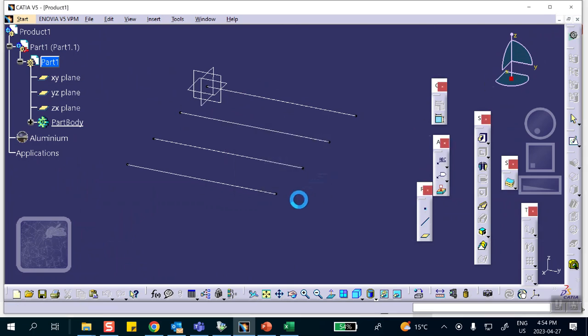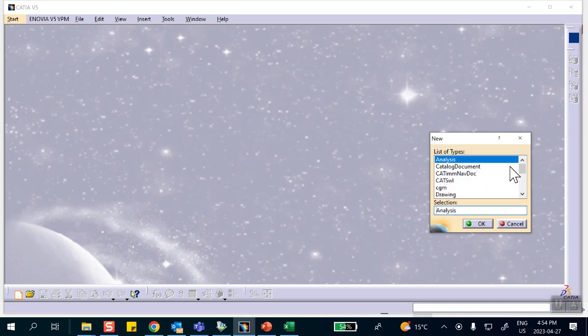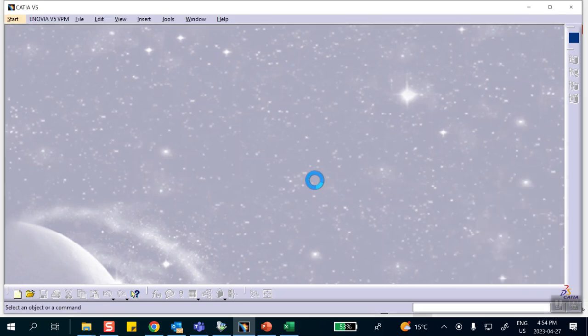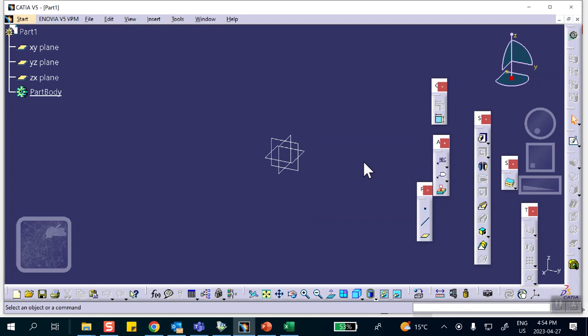All right, and we start with the part file. So let's start with the part file. I create my spring by first creating 2 points and a line in between them. Then, of course, I have to mesh that line with a beam element, but I'm not going to be using it. You have to do it, but you're not going to be using it. And then you create the spring through a user-defined connection.